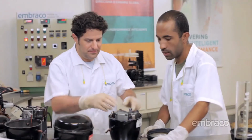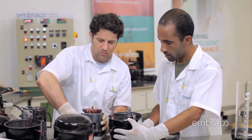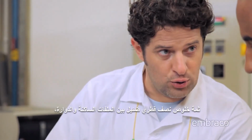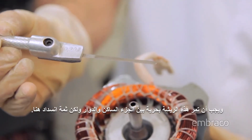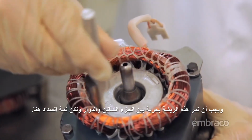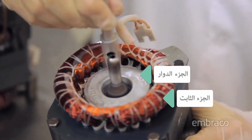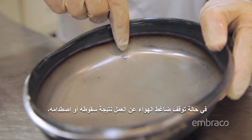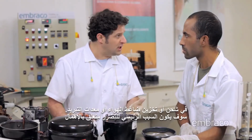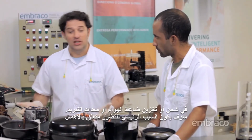Do you want to see it? There's a minimal radial clearance between the stator and the rotor. This blade should pass loosely through the stator and the rotor, but it's blocked here. If the compressor stops running from a fall or impact, the main cause of the damage is related to neglect in shipping or storage of the compressor or refrigeration equipment.